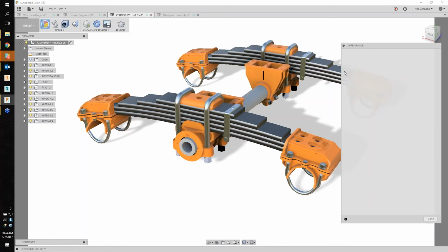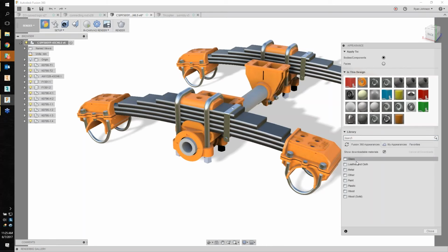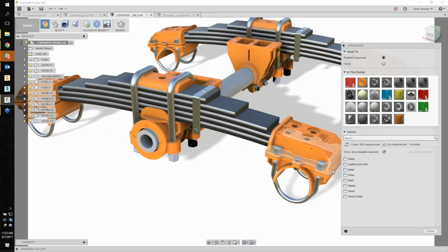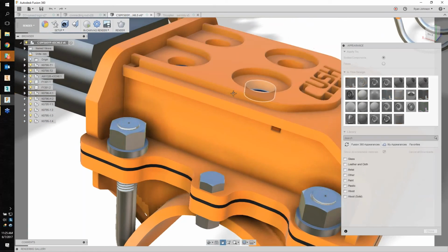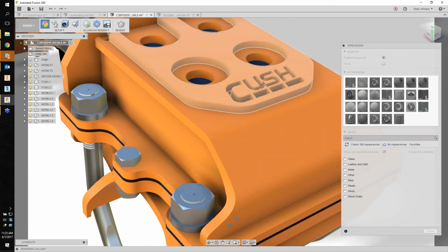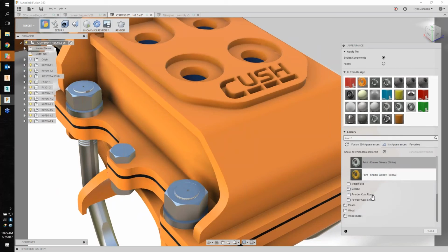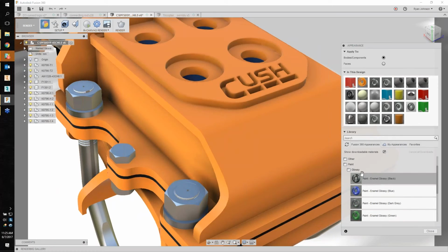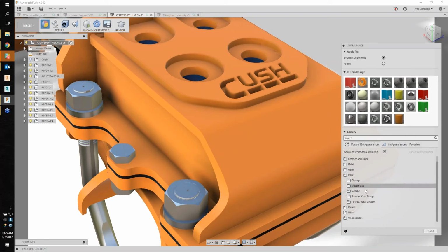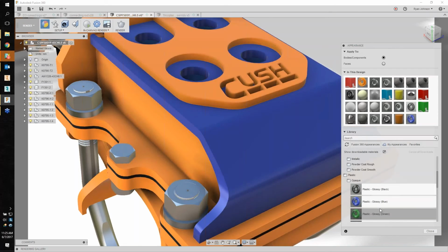To me, one of the coolest parts about Fusion 360's rendering environment is this material library they have. Even if you know nothing about material creation in a rendering tool, there is a huge library of materials available, and these keep getting updated. Every new update for Fusion, which as I mentioned is every 6 weeks or so, we get even more materials added, and even some pretty complex ones. So to use the new material, all we have to do is drag the material and drop it straight onto our model.